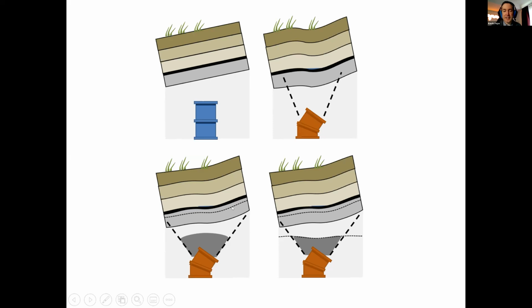I think this is a really important distinction. When we reinforce covers like this, simply because of the magnitude of the areas we're talking about, we do not prevent these voids from expressing at the surface. What we are doing is transferring them over a larger area. And there's a modeling activity. We have some publications about how you would go about quantifying that. Not going to go into the detail in the amount of time that we have today, but there is a way that you can quantify that spreading.